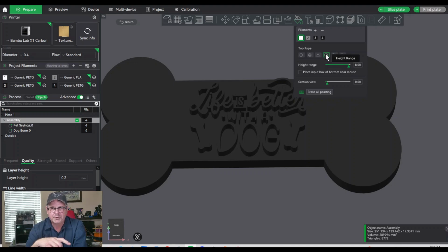If you have an Elegoo that's single filament, put a pause in there when it stops the black, and then change out the black for the white filament. So that'll give you your white print on the black background. And it doesn't have to be white on black. You can use blue on yellow, any colors. If you've got a team sport, something like that, use those colors.